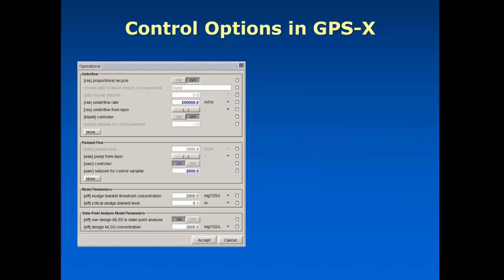The ones that are built in are present in most of the aerated type objects, such as the CSTR and the plug flow tank and so on, and all of the pump connection points. In GPSX, you'll notice there's a pump symbol on the object wherever there's a connection point that allows you to specify a pump flow directly. And in almost all of those cases, that pump can be controlled with a PID control loop.